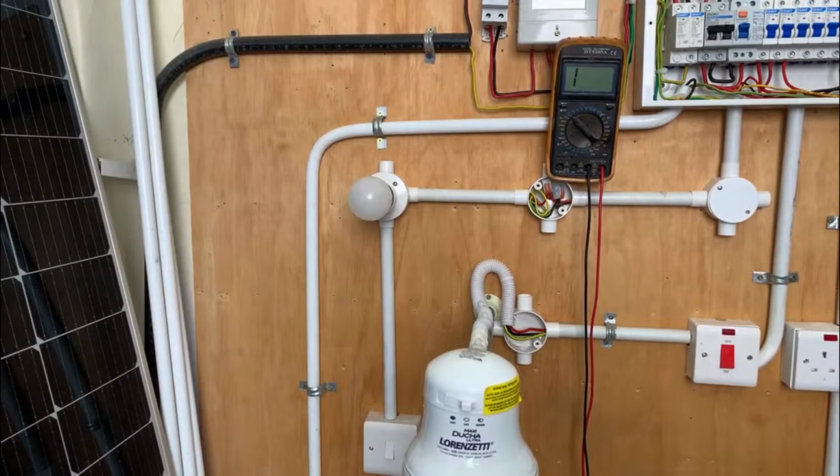It's all about coming up with problems that didn't exist, but that can exist. So we can short circuit the phase and the neutral at the lighting point, and then we'll demonstrate that indeed that is the reason why an MCB can trip, okay? So if you allow me, of course, I'll be very careful not to switch the circuit breaker back on when the short circuit is still there, until we sort it out with a multimeter. So do you give me a go-ahead, top bosses? If I get a go-ahead from you, definitely you're going to do that.